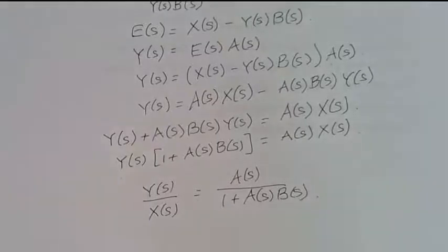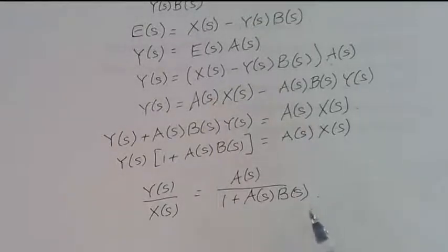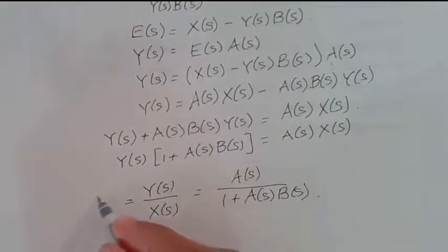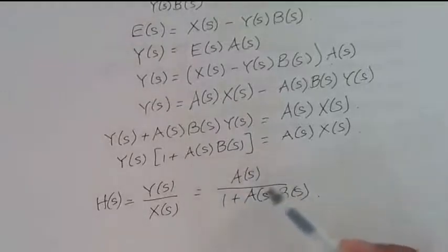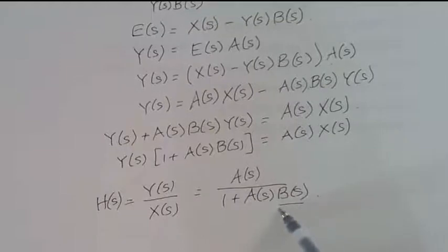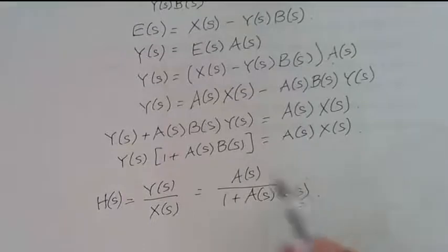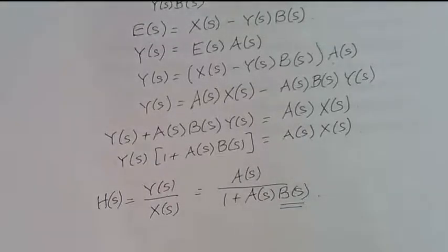Okay, so the effect of the feedback in the way that we've got it set up, and I'll show you one other way that people set these things up, is that the overall transfer function of the system with feedback is given by the original system that we had, which was A of S, and this other system that we put in the feedback path. Okay, so this is the general case, let's see how we can use this.